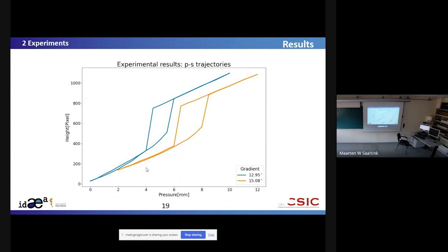I think the hysteresis in porous media, especially for two-phase displacement, involves the interactions of multiple pores, for example, pore-to-pore physics. For example, in drainage, the Haines jump breaks through into the neck, so the interface in other menisci will retract and refill. Yes, exactly. So this process involves the interaction between pore-to-pore and menisci. So do you have any plan to upscale this analysis?